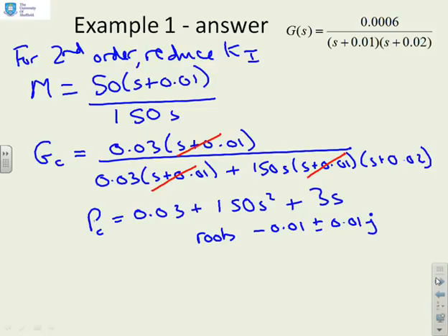So you'll notice they're now similar in magnitude to the open loop, and the damping is better. So in this particular case, the damping is acceptable. Only just, but it should be acceptable. So what we should do next is go to MATLAB and see, does the actual simulation back up what we are saying, the expectations that have come from our analysis on paper.